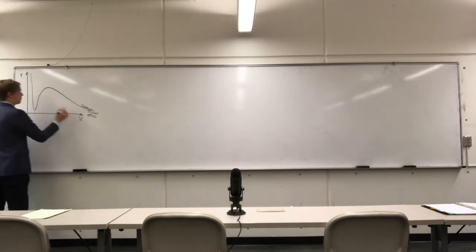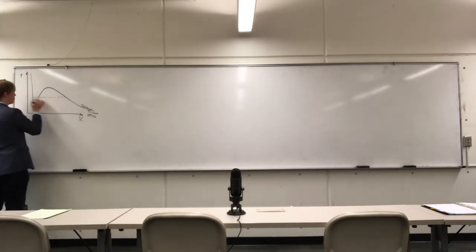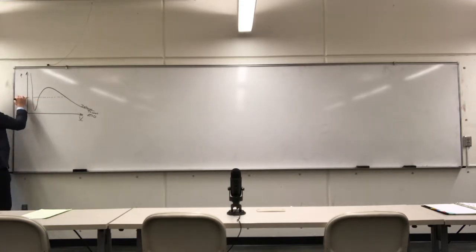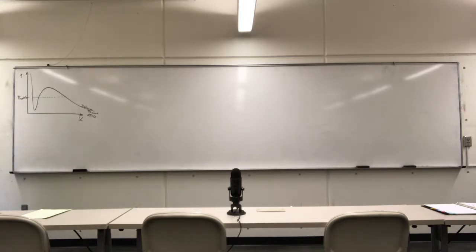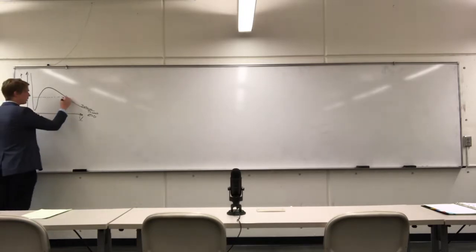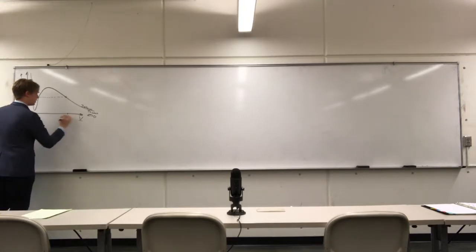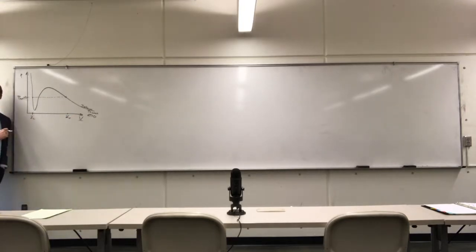The other problem is that when we draw out our dashed line here, this will be our vapor pressure at that particular temperature. This is one of our goals when we do a phase transition using a cubic equation of state: the density of the liquid and the density of the vapor are going to be off by a couple orders of magnitude as well.